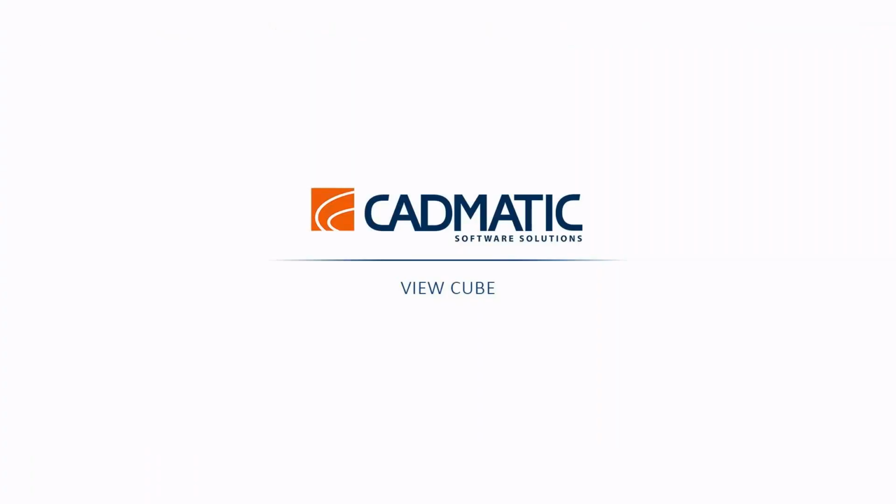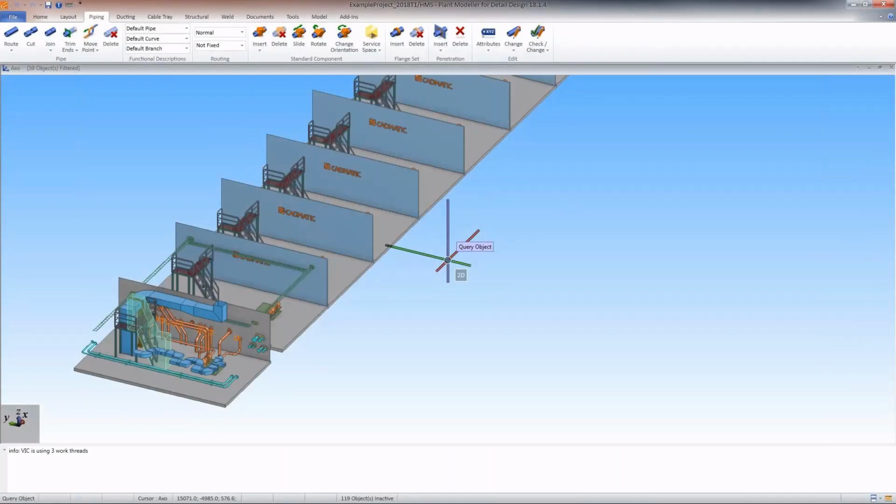In addition to using our mouse middle button to rotate our axonometric view, we can use the new View Cube functionality to quickly set our view from any face, edge, or vertex. The View Cube is opened by holding Control and clicking the mouse middle button.